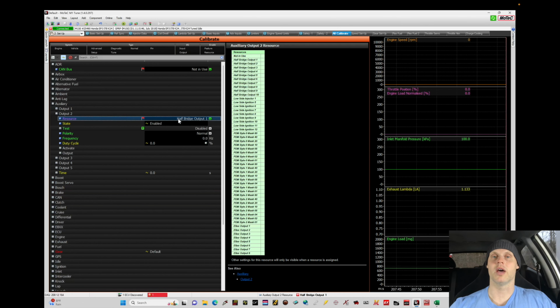and to engage it. And when we do that, oil flow is going to go through the oil passages into the galleys, into the rocker arms, and lock the sliding pin for VTEC to activate. Then when we want VTEC to turn off, we'll deactivate it here, and the slider pin will come out and the rocker will go back to the low cam lobe. So it's a pretty trick system. It's been around for a long time and it works great. And VTEC engines make great power for the displacement and the size of the engine.